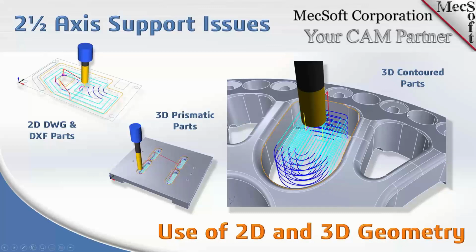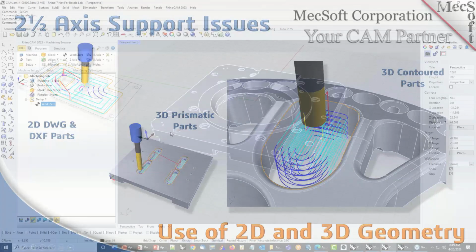Oh, one thing, go ahead. One thing, Don, I should mention: if you select 3D geometry like that, we will flatten it out, but also move it to the highest point of that curve. So that's where the cutting geometry will start, unless you tell it otherwise. Right, exactly. Okay, so that's basically the types of geometry that you will encounter in 2.5-axis machining.